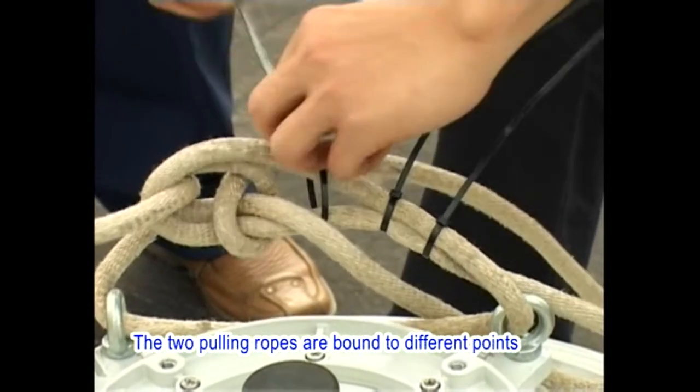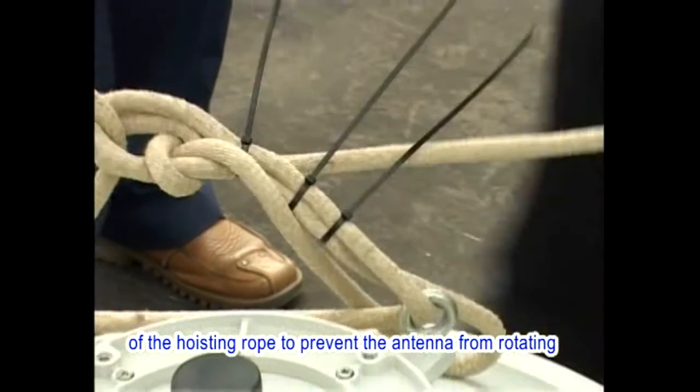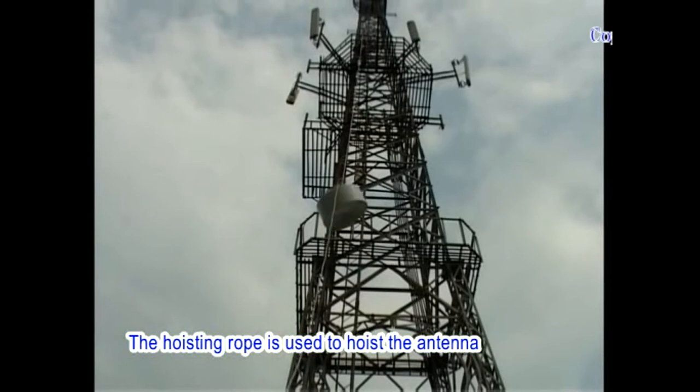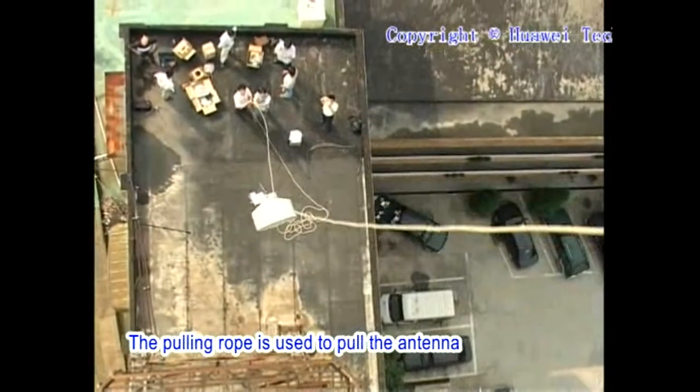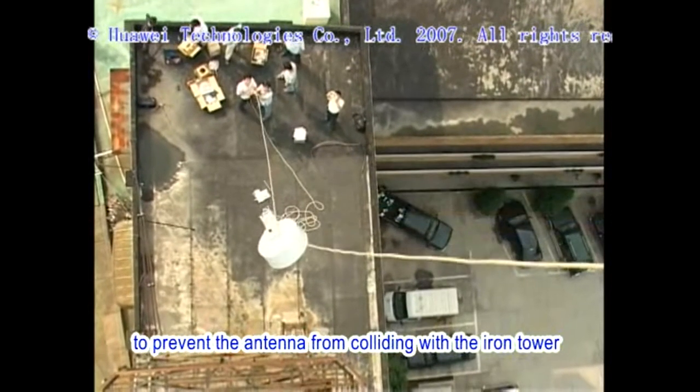The 2 pulling ropes are bound to different points of the hoisting rope to prevent the antenna from rotating when it is being hoisted. The hoisting rope is used to hoist the antenna. The pulling rope is used to pull the antenna to prevent it from colliding with the iron tower.